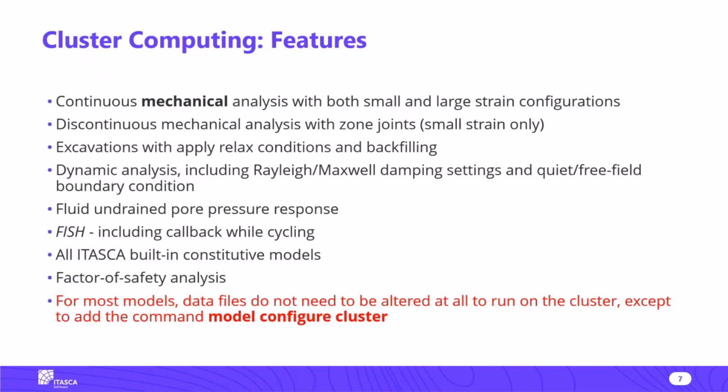You can do joints, you can have zone joints in there, you can do apply, relax, you can do backfill, you can do dynamic analysis, including all the different types of damping and all the boundary conditions. Even though you can't do fluid flow, you can have pore pressures. So you could specify a water table or similar to set up pore pressures. You can actually have changing pore pressures due to mechanical effects. So this would be an undrained response. That all works. Almost all of the FISH will work on the cluster, including FISH that is executed during cycling. All the constitutive models work. Factor of safety analysis works.